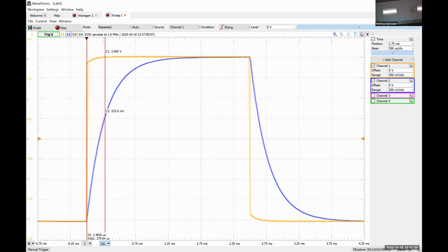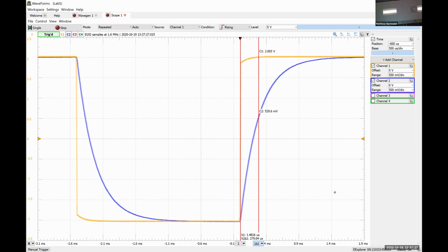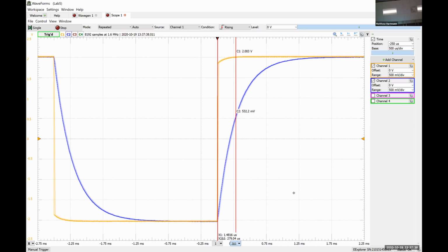And we can see now, this is looking at just a charge cycle, that we're giving our capacitor enough time to reach its final value, and then probably another half a millisecond or so, which doesn't seem like a lot, but for the component values here, that's enough time for it to finally settle to a value at what we're going to call y at infinity, right? And if we looked at a discharge cycle, we can see that it also follows that it falls down, and then it's able to maintain that final value for roughly half a millisecond. So this is a graph that we can actually analyze to figure out what's going on with our circuit.